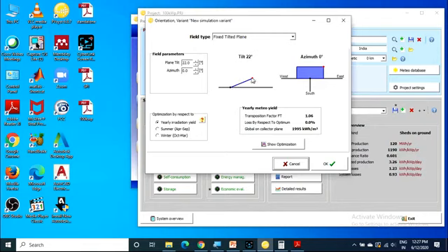You don't have to keep the solar module horizontal, on the surface. Then it will not collect the maximum power. So you have to place the solar module at some inclined angle. That inclined angle is nothing but the tilt angle. This is just a thumb rule: the tilt angle will always be equal to the latitude of your location.